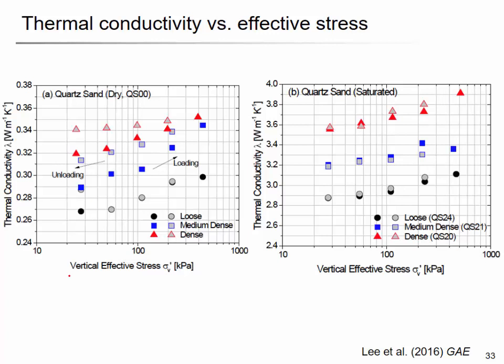So I brought the equipment that can measure the thermal conductivity. So this is the thermal probe, and we have dry soil and saturated soil. If you compare these, which one will have the higher thermal conductivity? Which one dissipates heat better? Saturated, right? Because air has low thermal conductivity, almost zero. The water has 0.5 watt per meter Kelvin. So if you measure it, this will give you about 0.2, 0.3. But this will give you more than 2.